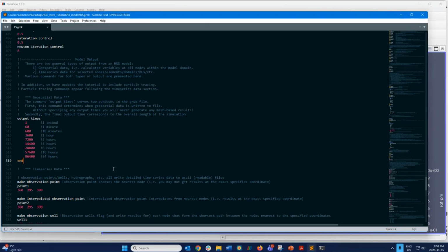There are too many variables to account for. Ultimately, the mesh resolution is entirely up to you, but you'll have to figure out a way to balance the practical needs of being able to run a model in a reasonable amount of time with your desire to have ever finer mesh resolution.